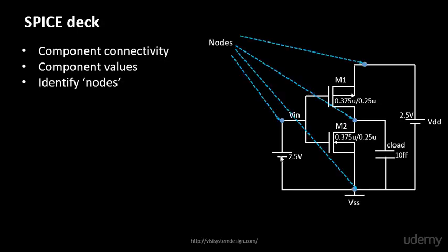In the past couple of SPICE videos we have looked into what a node means. A node means those two points between which there is a component. For example, over here this and this become a node because in between there is one component. In order to define a component in a SPICE netlist, you need to say that this component lies between this node and this node.